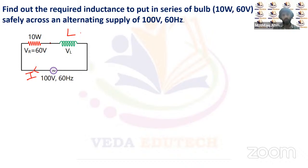There is some current flowing through the circuit, right? The same amount of current will be flowing through the resistor as well as the inductor. So we'll first of all calculate this current I. The total power consumption by this resistor is given as 10 watt. We know power can be written as V multiplied by I here.